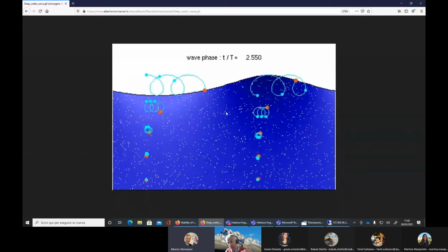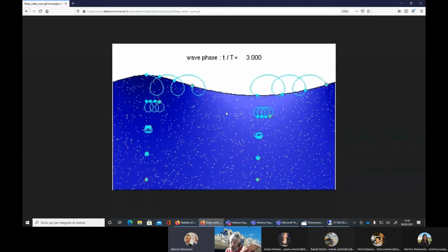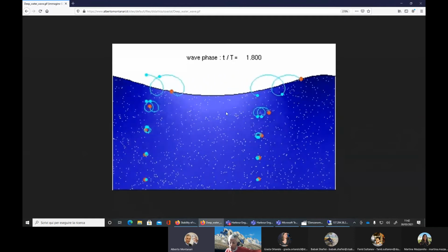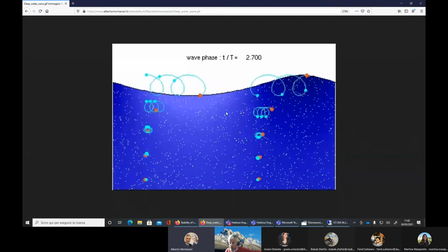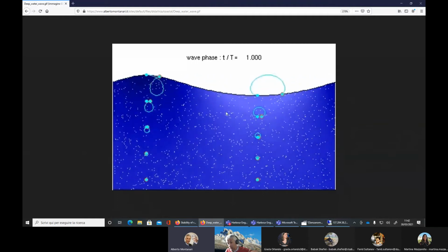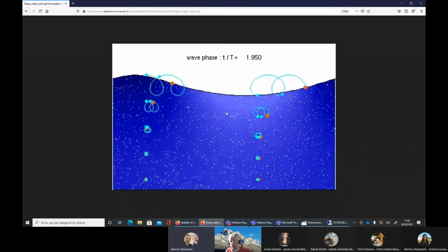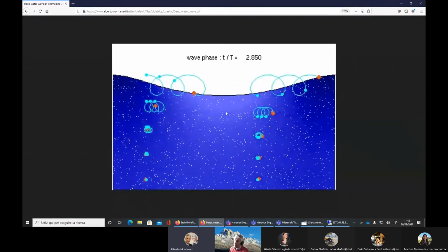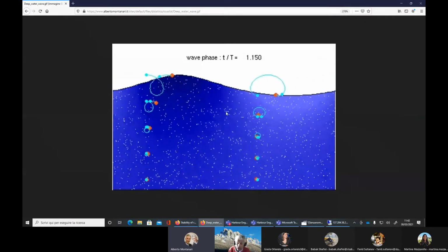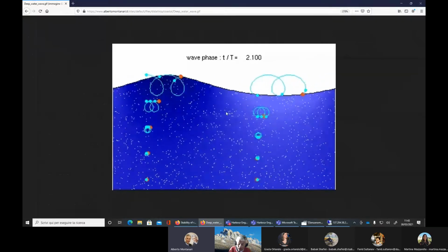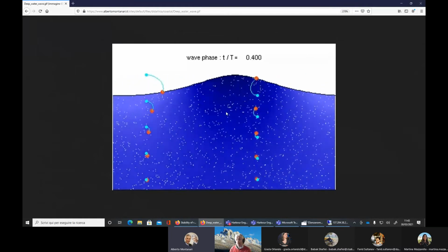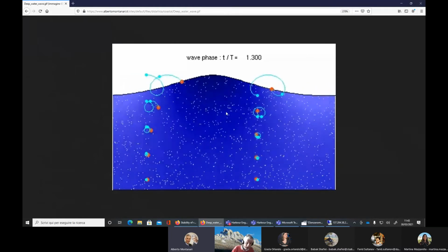Okay, you may say that if the groin is very long, then at the toe of the groin offshore, you may have the friction between waves and the groin before breaking. But in any case, the friction is much lower than the friction that takes place after wave breaking. So really with groins, we are not interested in estimating the shear stress induced by the particle velocity. We are interested in estimating the shear stress after wave breaking, and therefore we have to be able to estimate the velocity of waves after breaking.